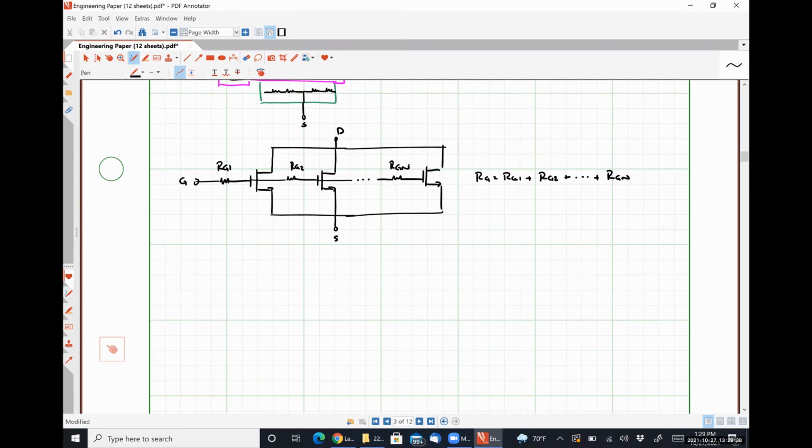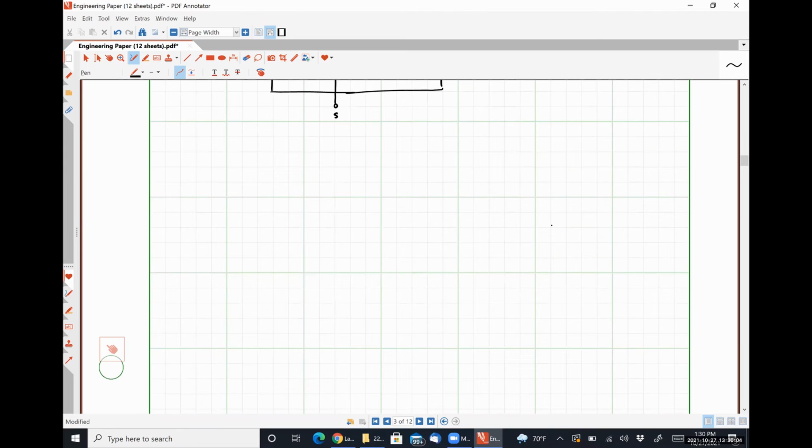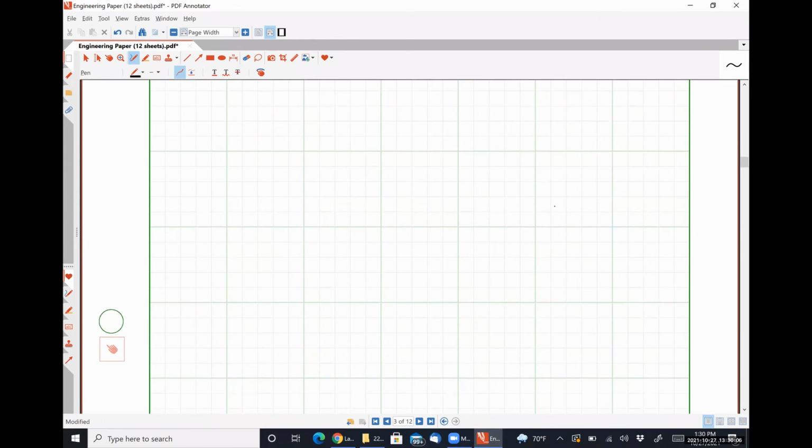If we were trying to model this as a single lumped resistance, what we should expect to see then is that the lumped resistor in our noise model will actually be less than RG because not all of RG sees all of the noise all of the time, if that makes sense. So we're about to do some math, figure out what that's going to look like, all right?